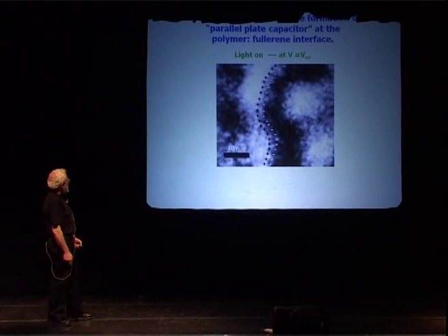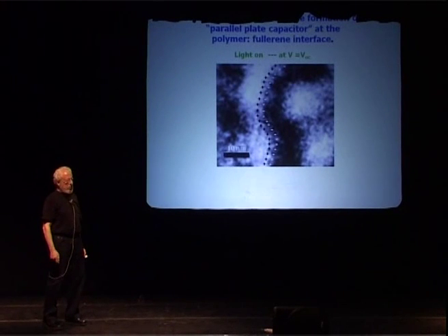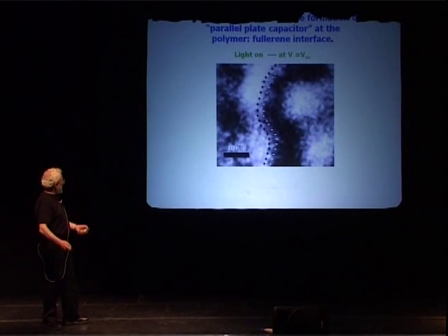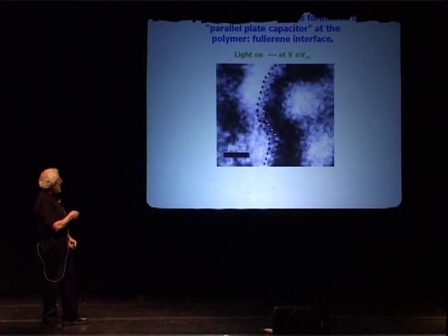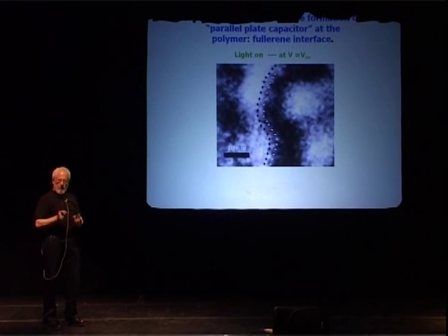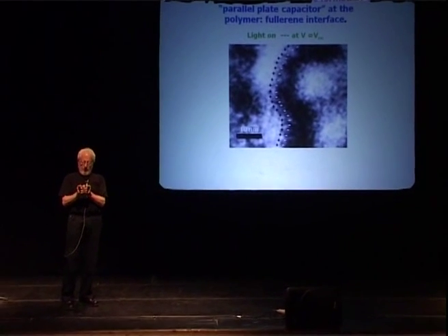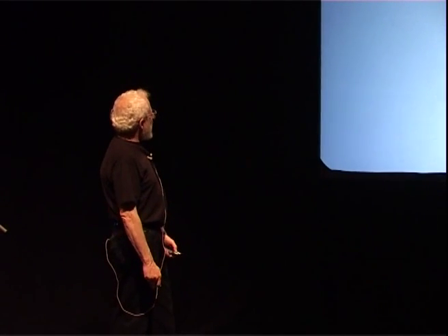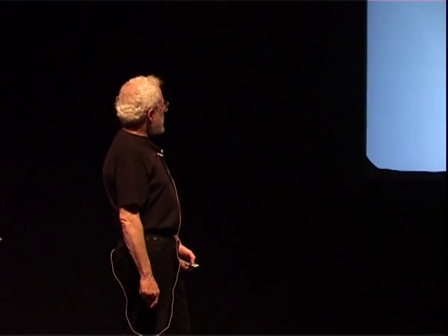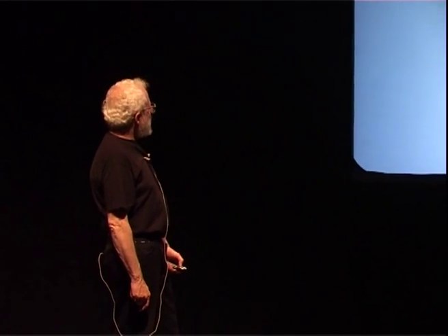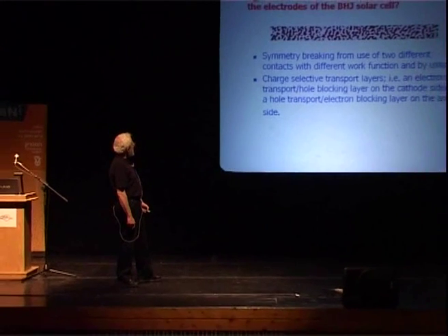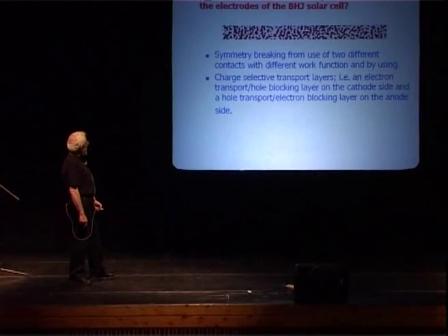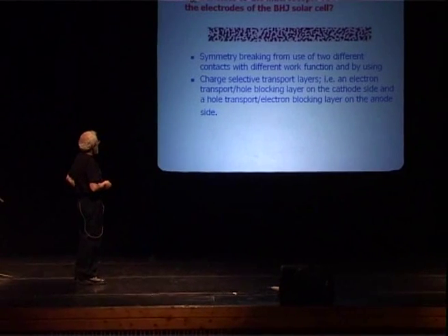So you have to build up this charge across the interface. The interface is a few nanometers wide at most, not quite molecularly sharp, of course, but nearly so. Nothing like the width in a doped PN junction. If the interface were actually sharp, if it were literally atomically smooth, then the width of that junction would be limited, basically, by the uncertainty principle. You have to have some spread. We talked about this. There's one other issue that I want to tell you about.